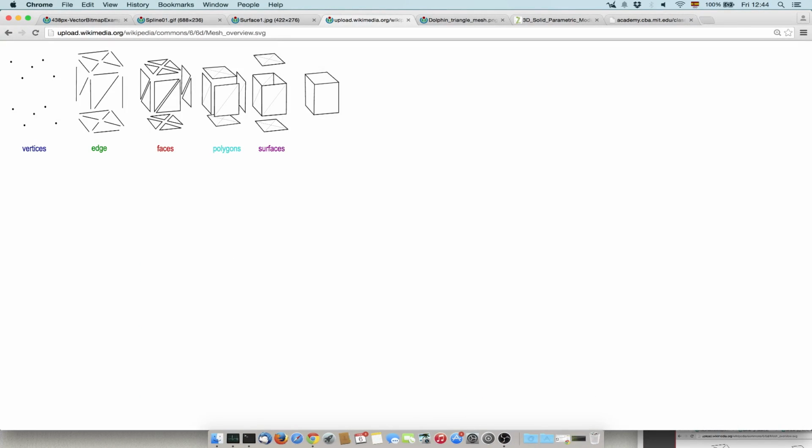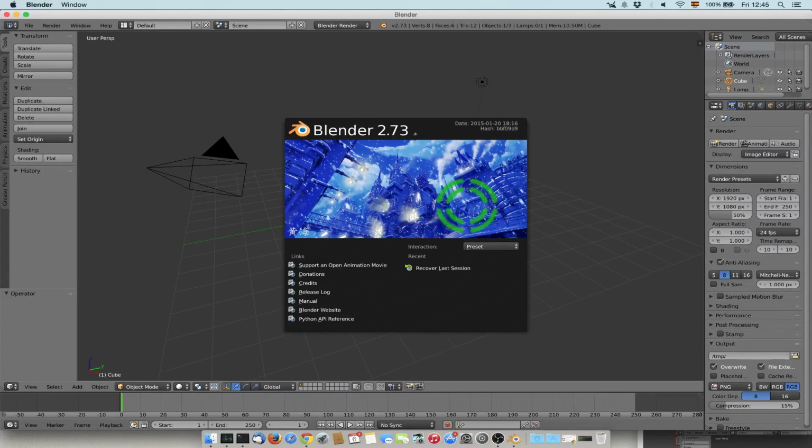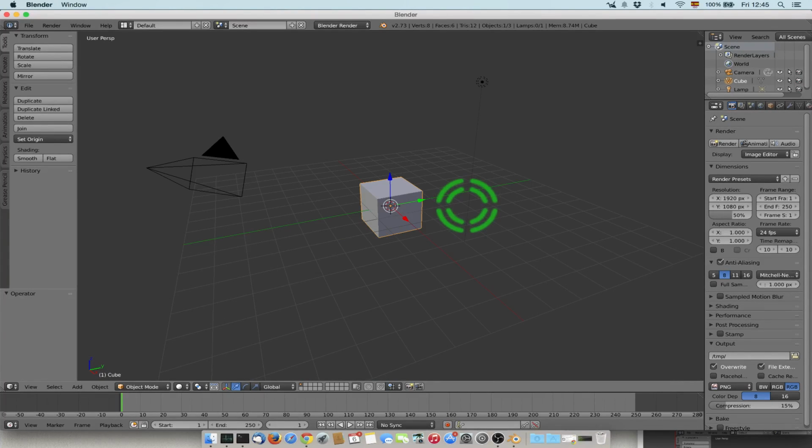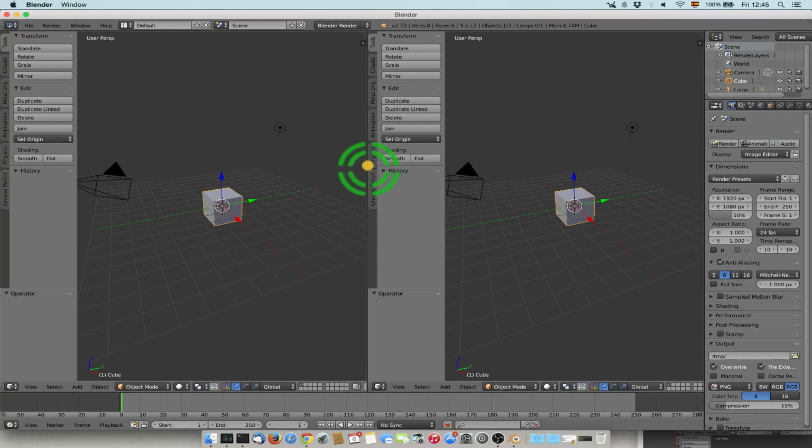Start Blender. The most important thing about Blender at the beginning is the interface, because it's very flexible. It means you can also configure it in any possible way. With flexibility comes a lot of power. Here you have the menu with some options and so on. Each of these is a different window, and if you click on the top right corner, you can multiply them. In this way you add a new one.